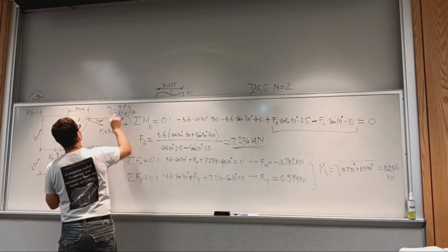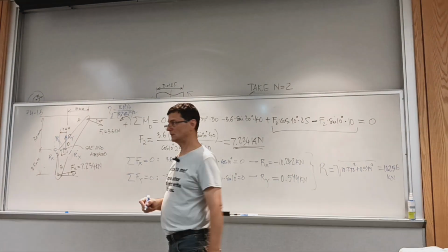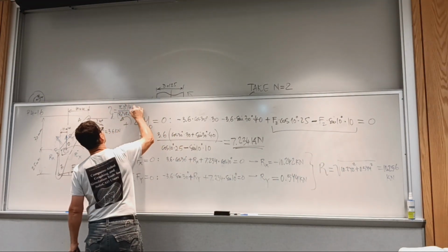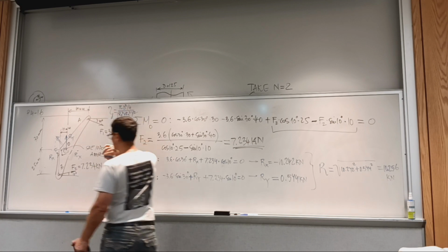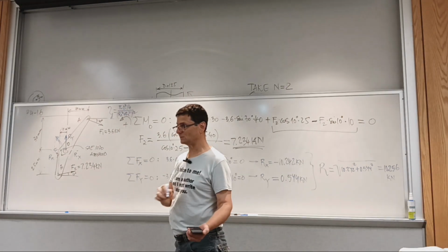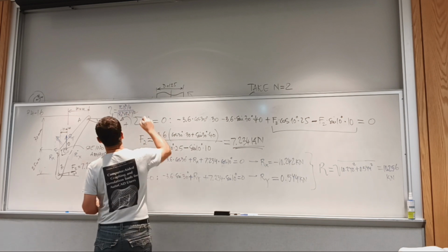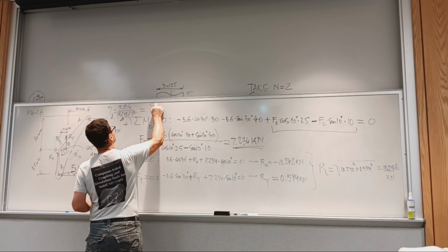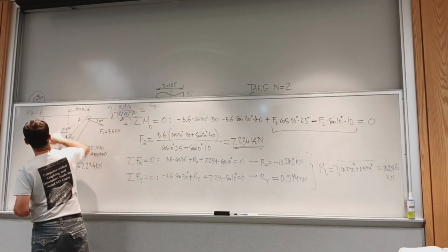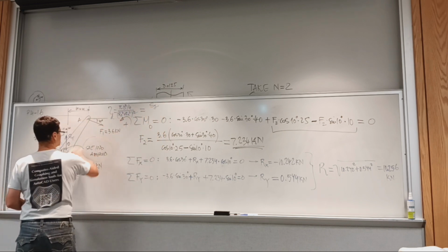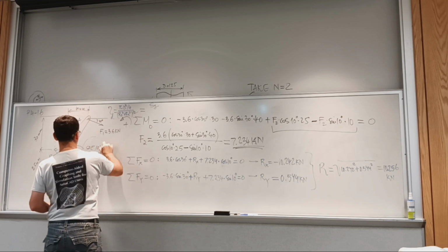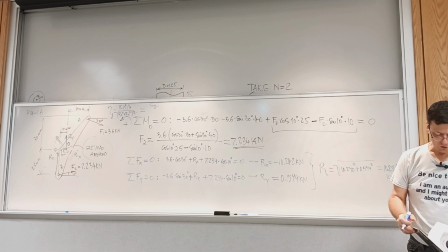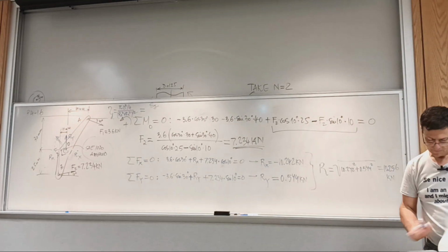Okay, so we can calculate the design stress in shear. Actually, no, we don't have a diameter. If we could do an analysis and report a design factor and see if it's a satisfactory one. So this is equal to yield strength in tension for the material, and I said I'm using 1020 in yield. What was that? Never wrote down. I just kept on justifying my choice for that new material.